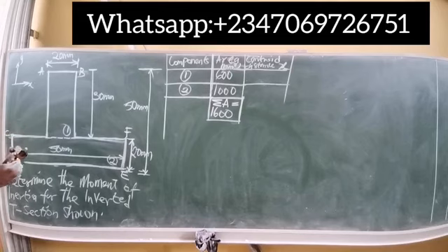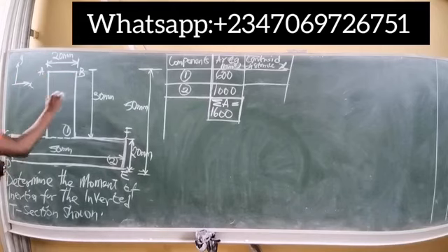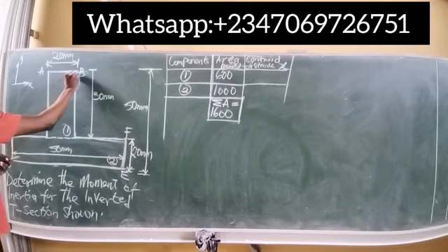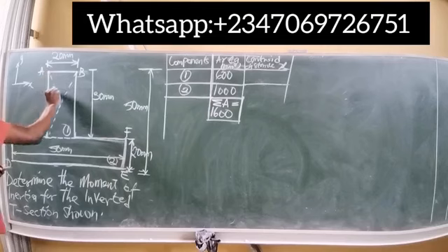So I want to find the central distance for the very first shape. It means I have to bisect the x segment into two. The x segment for the first shape is simply the width, which is A to B. So bisecting this into two, let us obtain the central point, that's the center of mass. Let's trace these points down and join them here. This is now the center of mass.